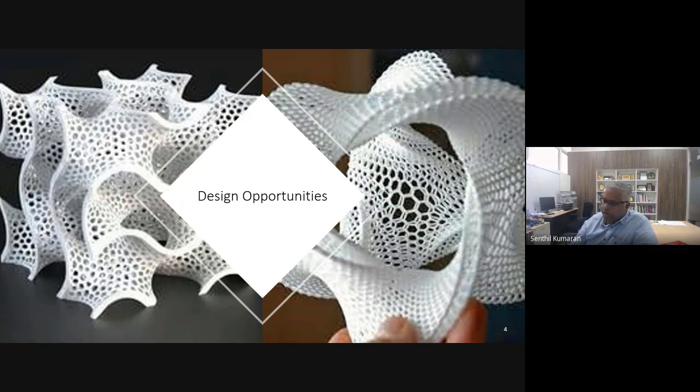See, if you look at it, it's a multiphysics problem. Both are multiphysics. Solidification is a multiphysics problem. There is a flow involved. There is a heat transfer involved. Convection, absorption, and then radiation, and then your phase change, heat of enthalpy, and then you have your Marangoni convection, and then flow behaviors. So all these things, if you can model them in a computer, you can understand how it solidifies.